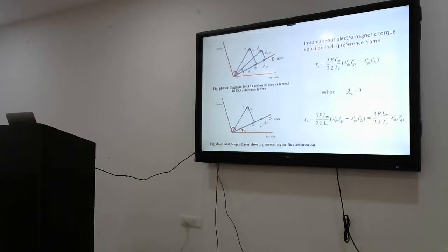See, finally, mentally what we are doing? Your 3-phase induction motor is basically nonlinear. Clear? But by using a control mechanism, by taking the combination of power electronic module and control logic, we are able to transfer the characteristics from 7th order to 1st order. 1st order is nothing but we are meeting the benchmark. What is our benchmark? A DC motor.